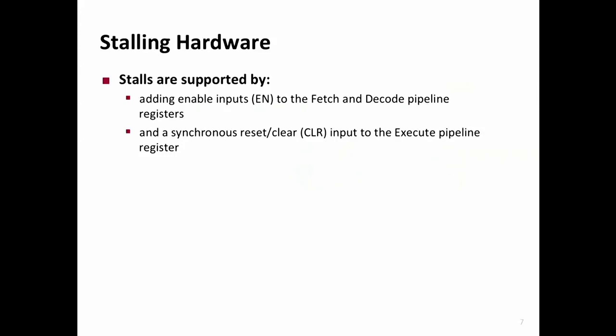The fetch stage, program counter, they have to stay there because the pipeline is not moving, right? That is done using the enable inputs. This could be done using clearing, or it could be done using an invalid bit associated with each pipeline register, whether the contents are valid, or the contents should update the architectural state when they go down. This is a more principled way, as I said. It's always good to think about principles, going back to lecture 1 and 2.